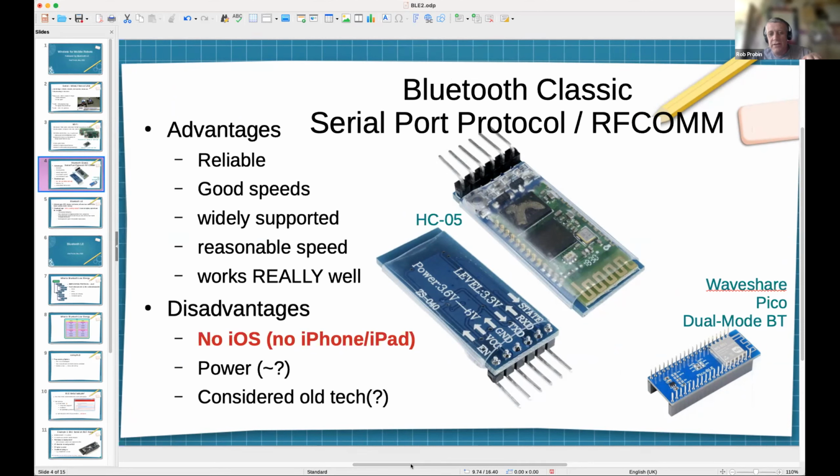Occasionally, to configure these when they're disconnected with Bluetooth, you can use an AT command session. Sometimes getting into that AT command session takes a bit of patience and Googling. There's quite a lot of pages about setting these things up. A couple of things are probably problematic.